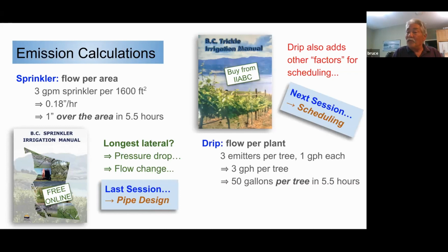So in drip irrigation, we're looking at 90% on our efficiencies, but we're looking at a system that is addressing the water specifically to that plant area, not the area in the middle of the panel. So drip can be efficient. In saying that, and I'm not advocating you should be doing this, there have been a lot of trials where they've used drip irrigation on everything from fields, hay fields, pastures, and the likes of that down in the south again, because of, in this case, lack of water availability. It's one way to address it.